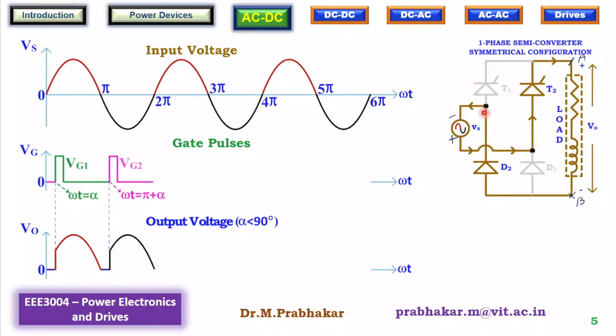Now please understand these things. When you draw the circuit diagram, a jump over here is required, or put the supply here like we do in simulation. There should not be any joint or other things. If you have a node over here, then the circuit is wrong. You should not have a node, you should have a jump. That is why for clarity I have put both dot and a jump. You should not have a dot here. These things might look silly, but students keep doing such things.